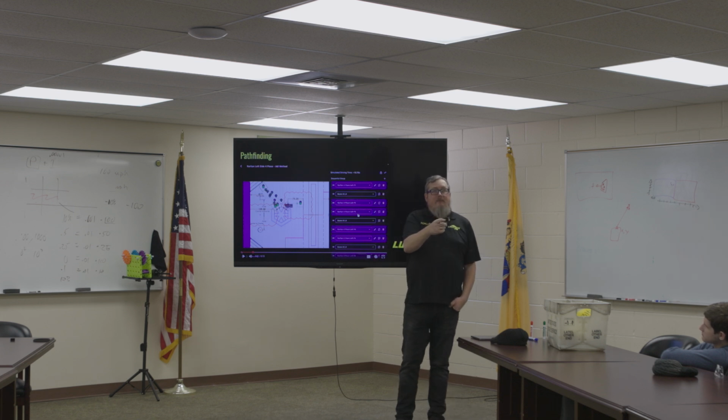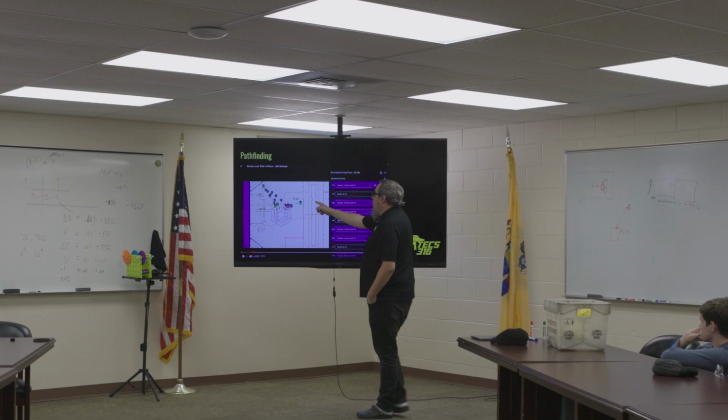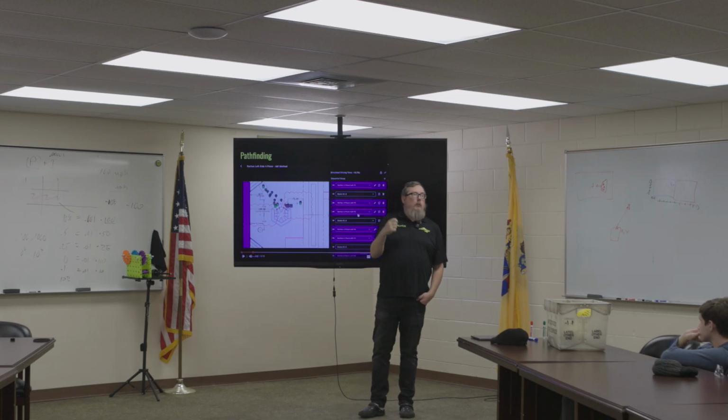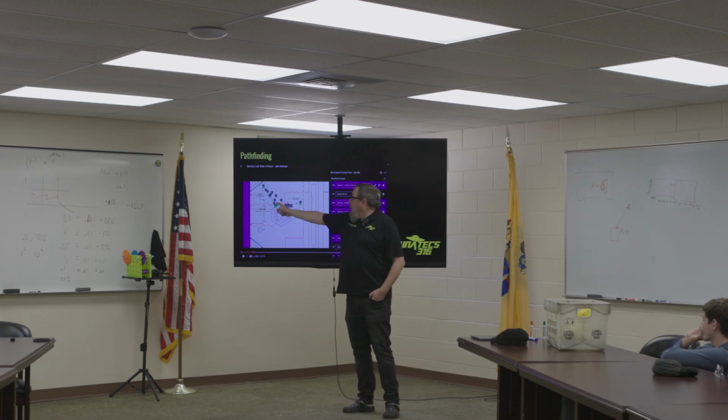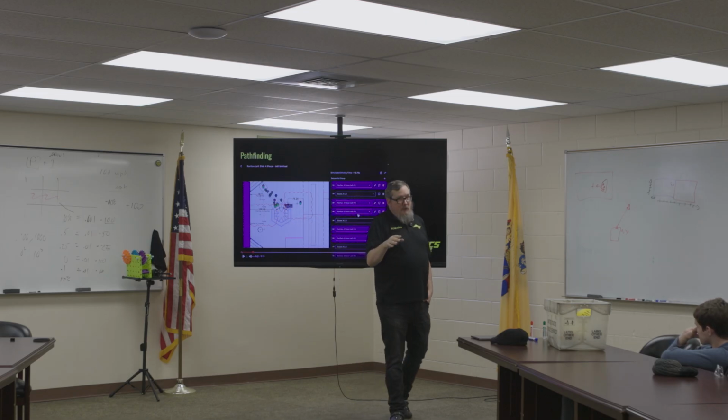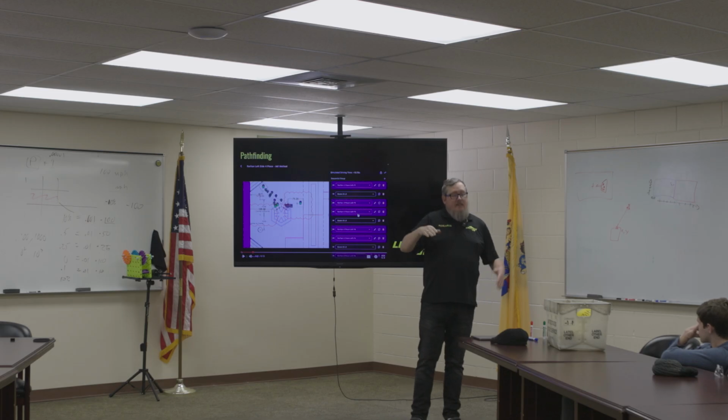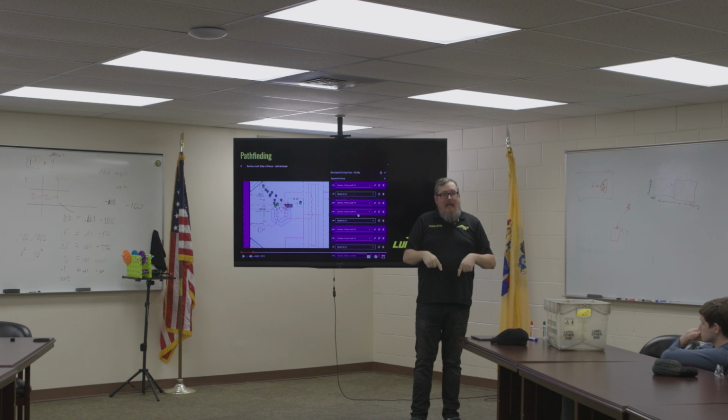Every event marker gives the robot a position and a rotation that it has to be in. No, it's telling it to shoot out. Right. So each event marker is us giving the robot a command to run. You'll notice that there's one here, here, here, and here. When we get there, the path will stop, run the command, and then when the command ends, it will proceed to run the path again.